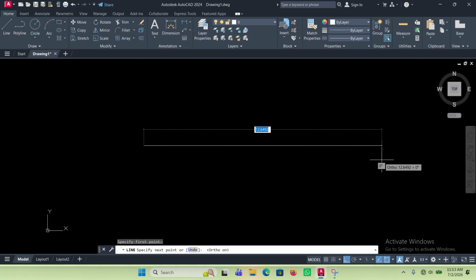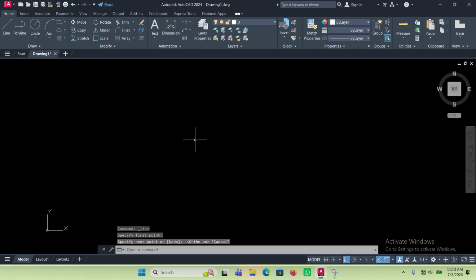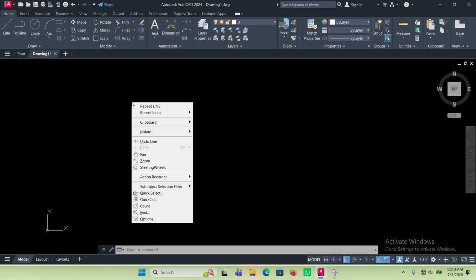So you see, if you type 5 meters, it will be so long. So sometimes it's good we just zoom the page so that when you do a drawing, it will not be extra long. You start looking for where it runs to. So in this case, just press escape from your keyboard, and then you can type scale, or you can right click and then select scale.